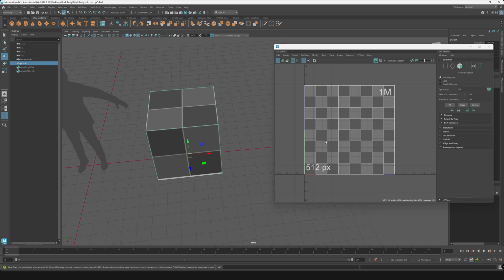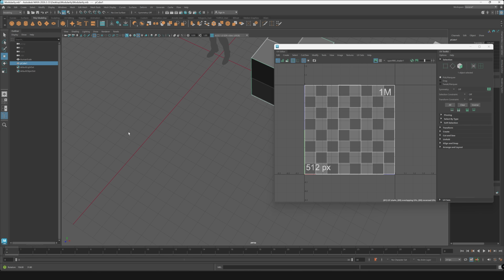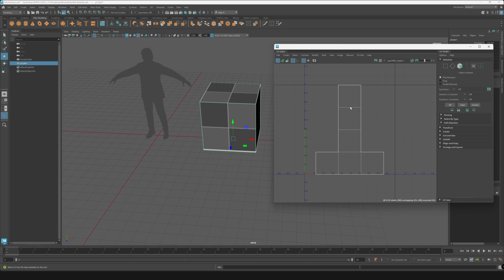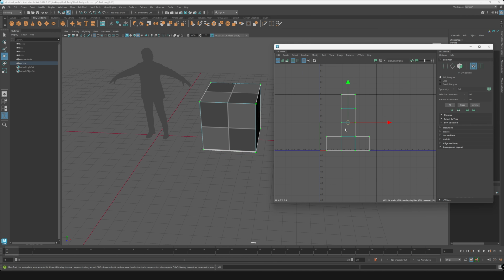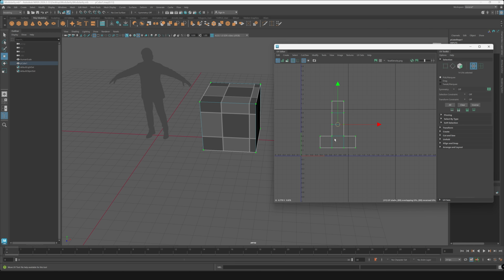And we need to make sure that our texel density matches the proper scale, aka every single one of these faces on this cube is 1 meter by 1 meter in dimensions. So we need to change that. And the easiest thing to note is one of these UV tiles will fit an entire 1 meter by 1 meter dimension of data. So all you gotta do is rescale one of these faces to match that.